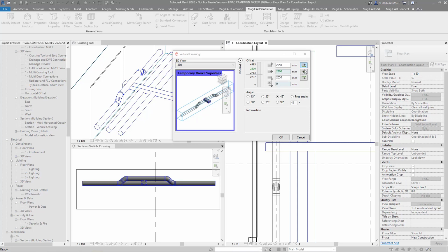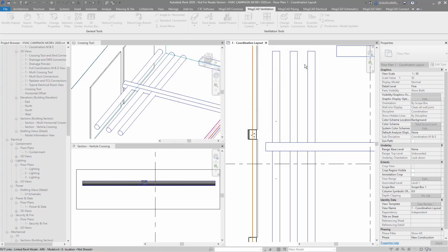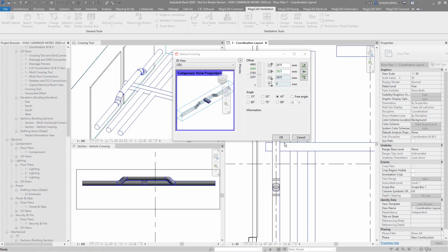So what I'm going to do is I can use any of these. I'm going to click on top of, and I'm going to re-reference this duct. Now what I've done there is that duct is running exactly straight on top of that one, which we won't want. So I can then add this tolerance here. So I can put 100 mil on top of that. And as you can see, it's all live updated, and now I've got 100 mil tolerance between the duct I'm amending.